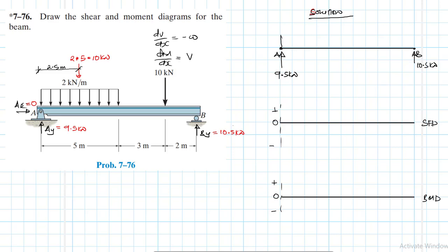And then we have a distributed loading, let's say up to half the length of the beam, somewhere there. This is a constant distributed load, or rectangular, which is 2 kilonewtons per meter. We also have a point load, a concentrated load, somewhere there of magnitude 10 kilonewtons.